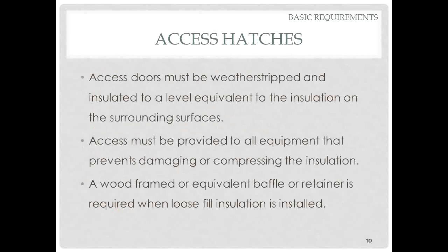There's a little detail on access hatches that's new this year. Access hatches must be weather stripped and insulated to a level equivalent to the insulation on the surrounding surfaces. I emphasize that a little bit because that's a rather stringent criteria. So this means, for instance, that your attic hatches are going to have to be insulated to the same level as you're insulating the attic floor.